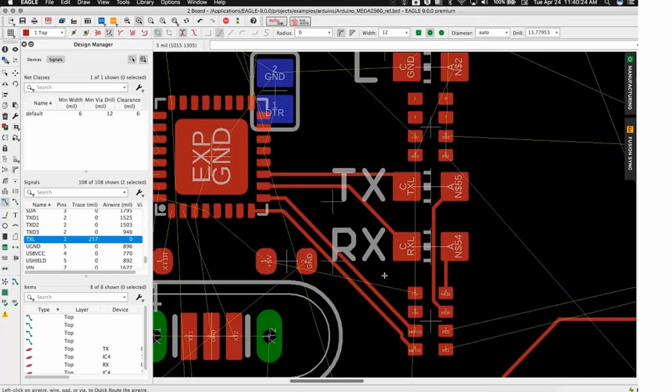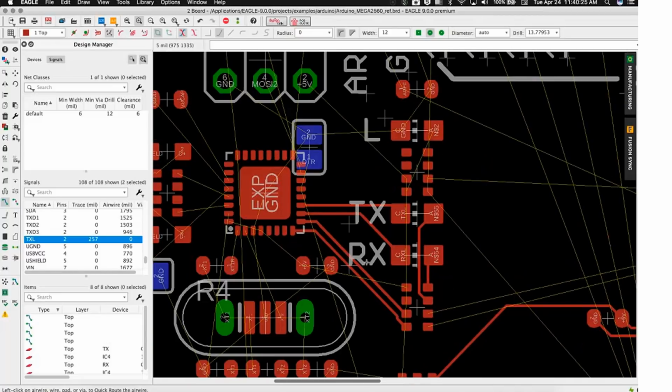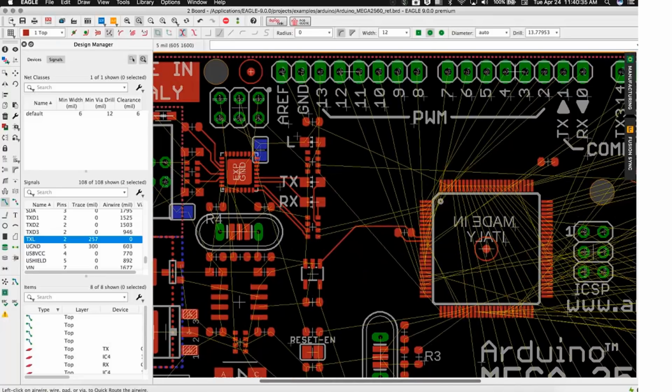I don't really have to think about the connections that don't add a lot of value in my design. Any of these very simple, straight, point-to-point connections are very easy to route using quick route air wire. Now, if it's a little more sophisticated, with multiple nodes on the net, and you're saying, hey, I'm fine with quick route just taking a shot at that signal, I can click on something, click here, and the quick router will route that whole signal. In this case, that signal is not just the air wire, but there are multiple air wires along the course of the signal path.